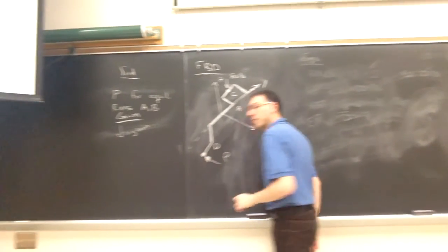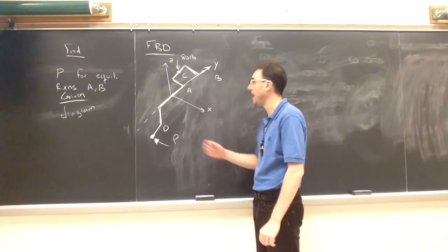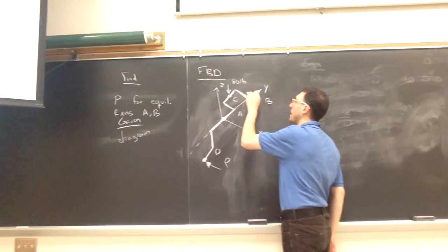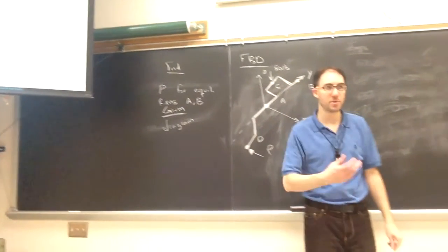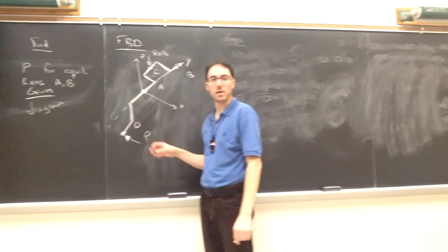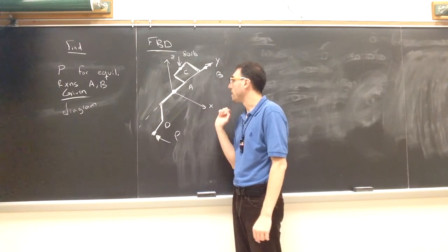In drawing my object, I've included those two applied forces, the 80 pounds and the force from the hand at P. But I have a bearing at A and a bearing at B, and we need to include what those two supports that are not in this picture are doing to the yellow shaft that we did keep in the picture. We'll begin by looking at A.